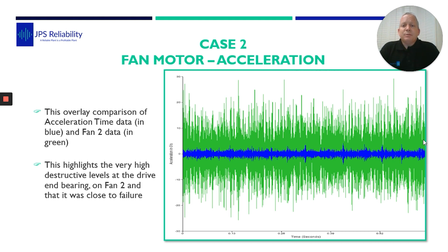This is the initial vibration data. This is the acceleration time waveform. And I must say, the time waveform is where you really should be doing your analysis. This is where all the information about what the machine is doing is at.